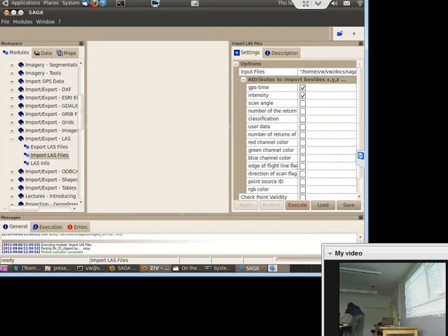Did you manage to import the data? Parameter file. You need to provide it here, select it, and then execute. So, okay. There would be a lot of other interesting things too, but you can explore this file yourself. You should be able to load it now, did you? Okay. Yeah, copied it. Great. So you can simply go to the File menu, Load point cloud, and load this data set. So you have it too.